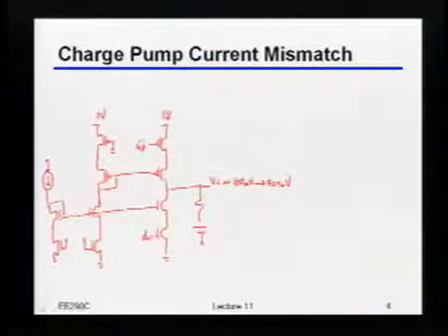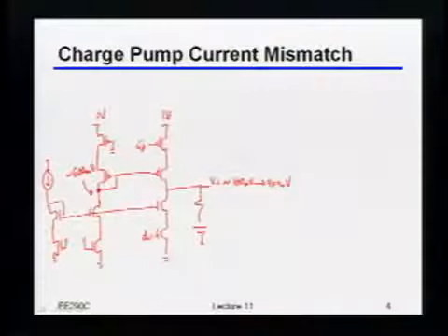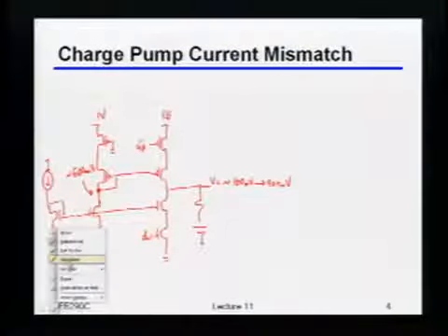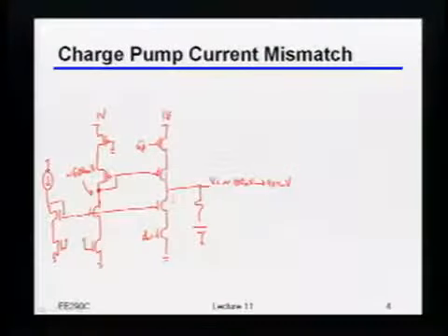On the lower end of a control voltage, your pull-down current will be lower than the... Yeah, that's right. Basically, we're starting to squash out that bottom current source, right? Just to make that clear, if I look at the biasing branch, the voltage there is approximately 600 millivolts, right? So clearly, when I do this mirror over here, the current I get through that PMOS is not at all the same as the current I got through this PMOS. Not to mention that the NMOS isn't really the same as this one either, because the biasing may not be good enough, the output impedance may not be good enough to really tolerate that, okay?